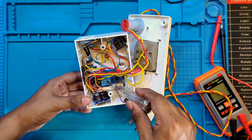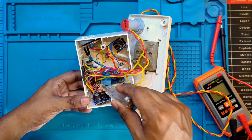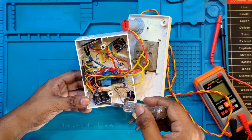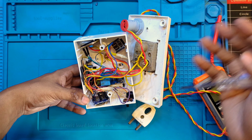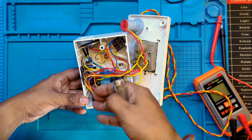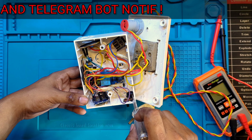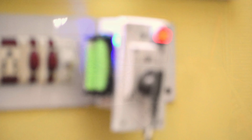So this is the main current sensing part. What it does is take the AC input and provide a compatible 3.3 volt analog output, which gets fed into this ESP8266's A0 analog pin, which then processes it. Based on the loops and the conditions put in the code, whenever that sine wave or that analog signal of the AC current gets lost, we get the notification in both the speaker, that is the voice command, as well as the buzzer format, and whenever the current comes back, it again starts to read the analog signal.